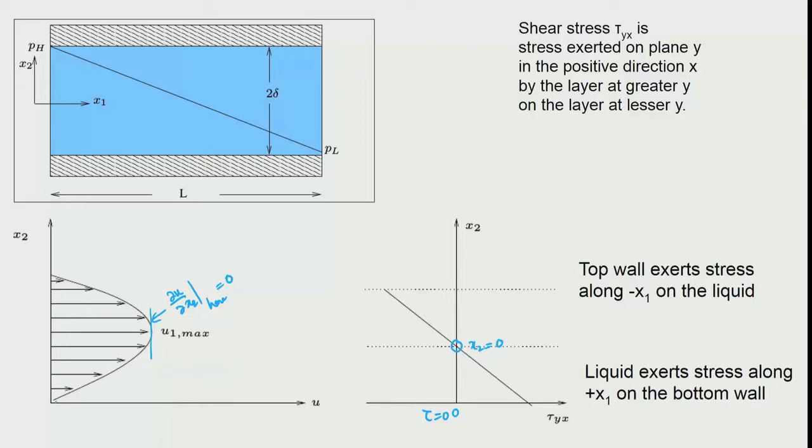Now, you could also see that at the bottom layer you have got a positive slope, and you have got positive stress here; here I have a negative slope, you have got a negative stress value there. So, you could actually predict the stress profile from the velocity profile. You could also plug in the mathematical expression and arrive at the same thing, and you could also apply the definition here and convince yourself that the reason why the stress is given in this particular manner is actually valid.